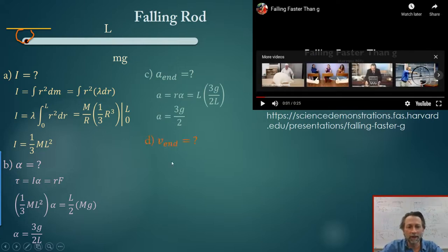So moving on then, if we wanted to find what's the actual velocity at the end of the rod, we can say, well, hey, there's a certain amount of potential energy in the rod. And when the rod gets down to straight up and down, all that potential has become kinetic rotational. So mgh = 1/2 I omega squared. We can plug in our mg.